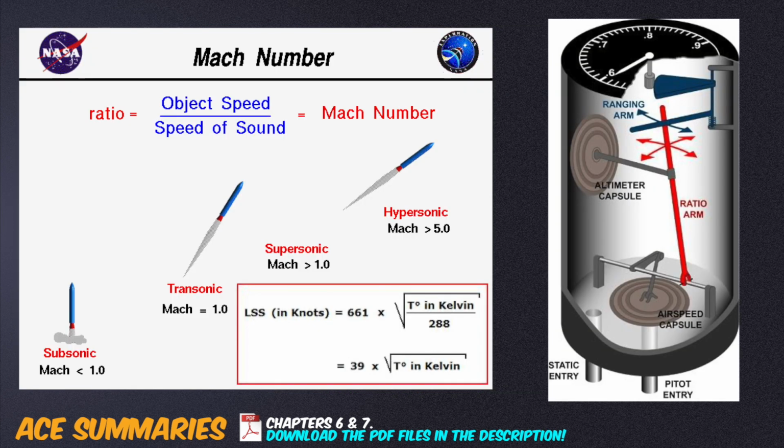Mach number is a function of temperature and true airspeed. Aircraft flight instruments, however, operate using pressure differential to compute Mach number, not temperature. What this means is that a Mach meter is essentially an airspeed indicator with an integrated altimeter element. The Mach meter does not suffer from density or temperature errors for this reason. The instrument or pressure errors are negligible. Modern Mach meters use the air data computer for its inputs.